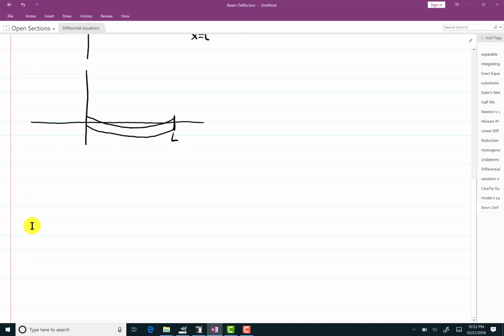So let's take a look at what can happen when a load is applied. And remember, my pictures are gross exaggerations of what actually happens. So in a situation where we're embedded, we might have something like this. It'll be straight because it has so much reinforcement near the wall. And then it might dip in the middle, but then come up and flatten out again at the other brace.